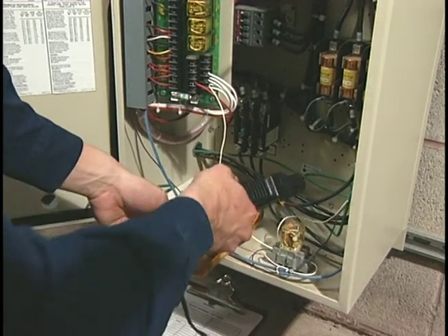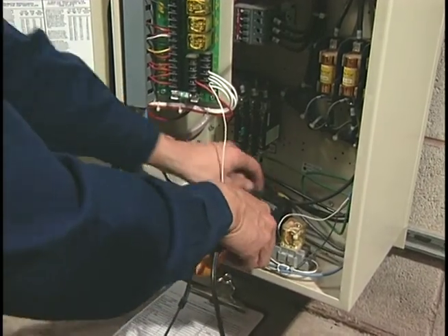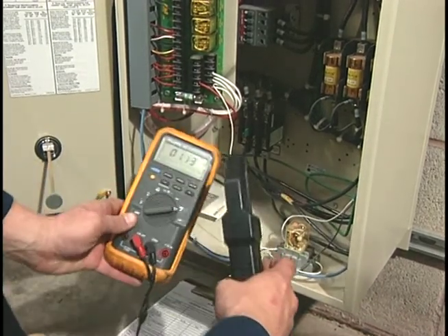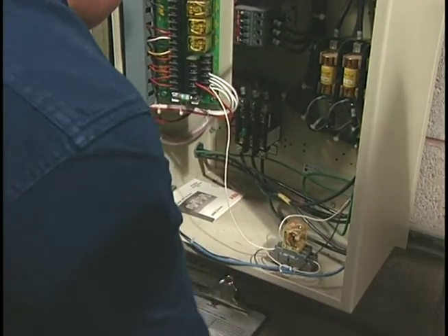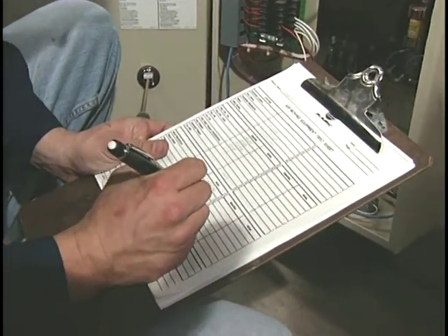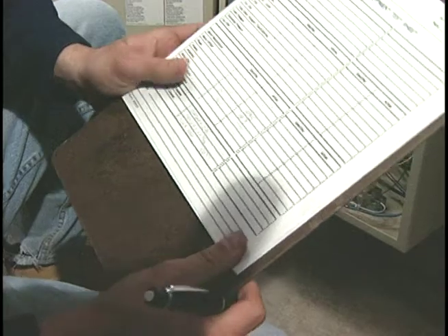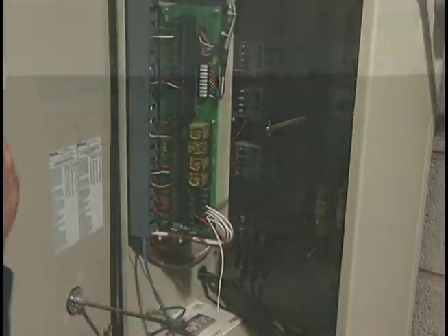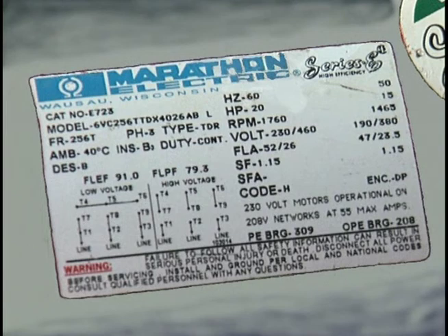Only one reading is required when measuring a single-phase circuit, and that reading can be on either the hot wire or the neutral wire. The technician records the readings as actual amperage on the appropriate forms and compares them with the specified data. To be acceptable, the current measured on any phase should not exceed the motor nameplate amperage. If the current exceeds nameplate amperage, the technician will consult with the appropriate responsible person.